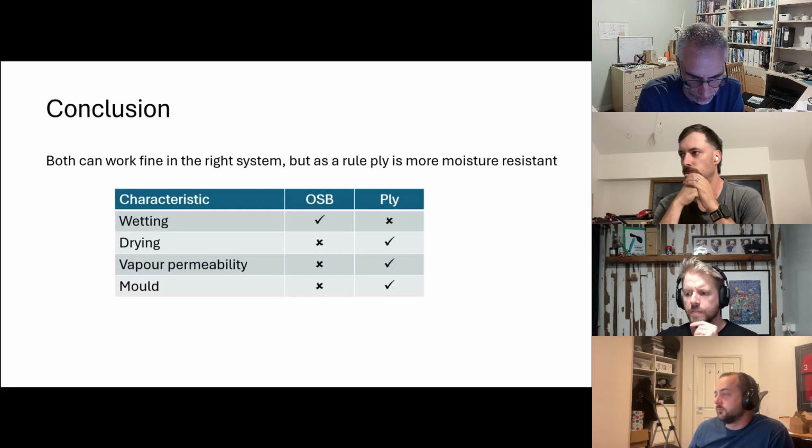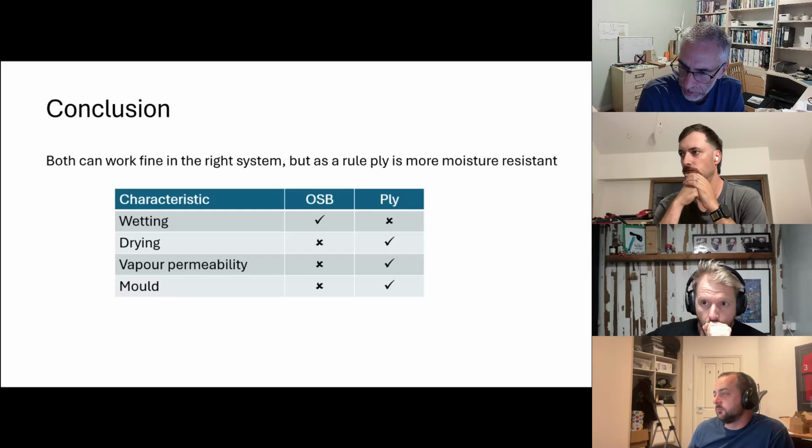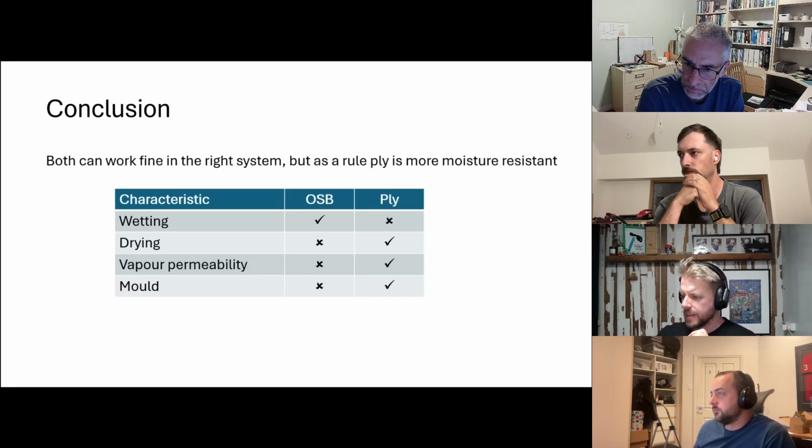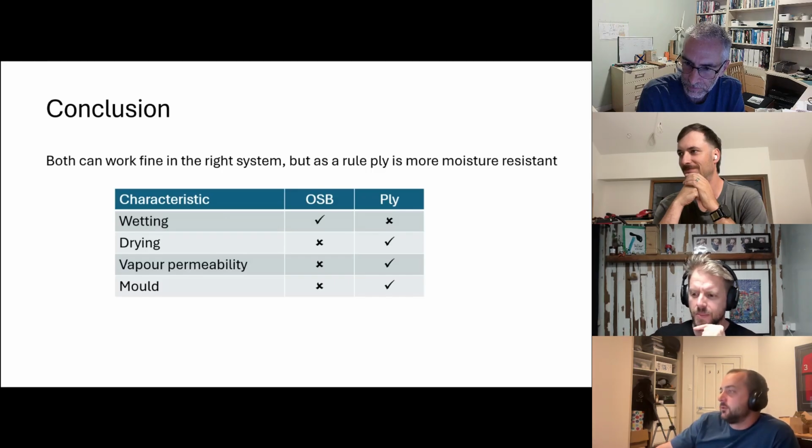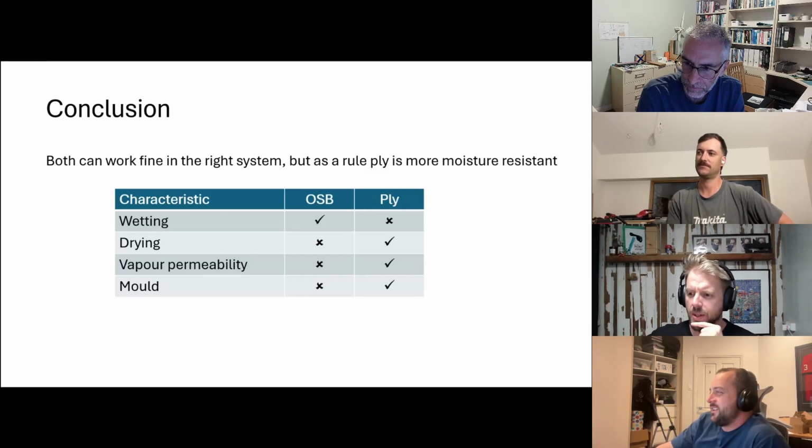And there's a few other brands, I'm sure, of various sorts of boards out there. They seem to be more targeting the commercial market. They've got pretty good vapor permeability from what I remember, but I don't know the numbers off the top of my head. And I don't know what they do structurally. Are they any good as a sheathing? I'm sure they're doing something, but intuitively, I'd rather throw Ply and OSB up, just because I'm used to throwing timber on my walls rather than a cement sheet product or a fibre cement sheet product.